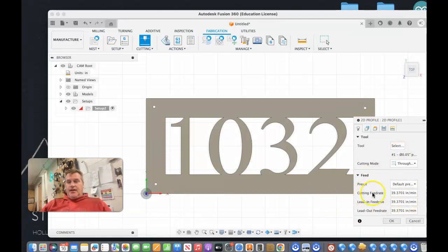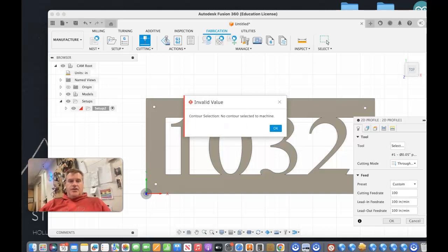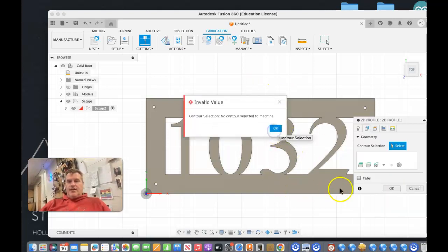So that's all set. Here, the feed rate, we are finding out that going this slow, going 40 inches per minute, it's just going too slow, and it's really just kind of melting our steel and making a lot of dross and making a lot of cleanup later on. We're going at 100 inches per minute, and that's pretty good.